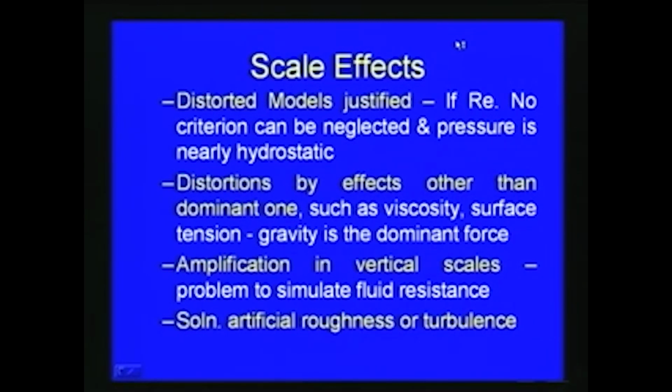When we use a distorted model, there will definitely be scale effects, so we have to consider the scale effects. In many cases, as I mentioned, we cannot achieve all the geometrical similarities, and that is why we go for the distorted model. Before going for a distorted model, we have to justify whether this kind of modeling, the money, time and effort invested, is justifiable or not.